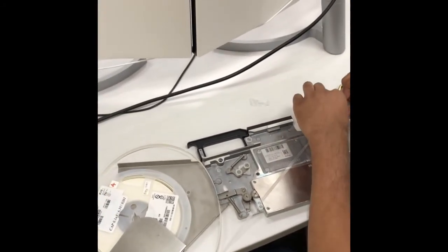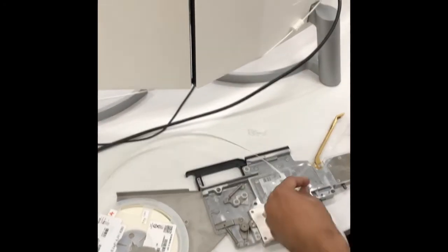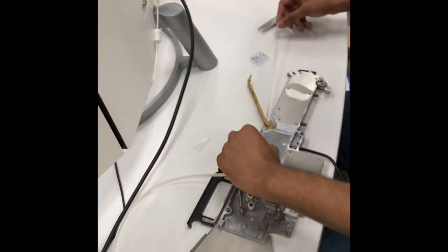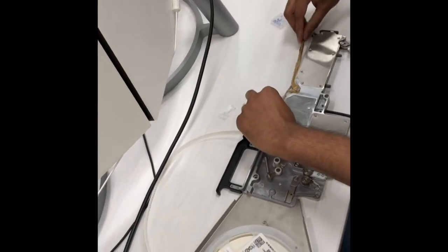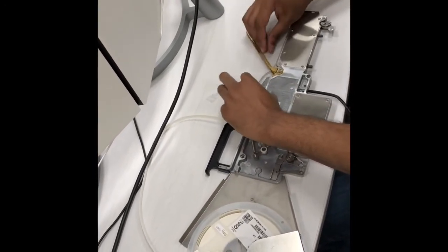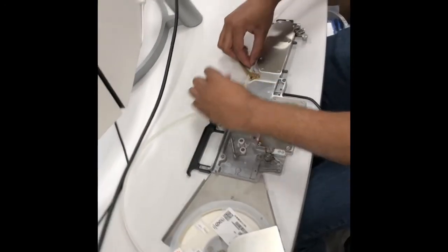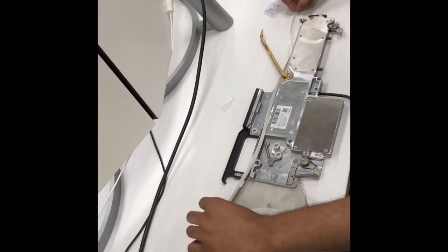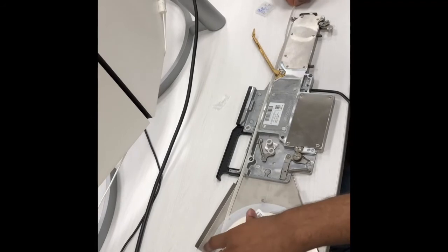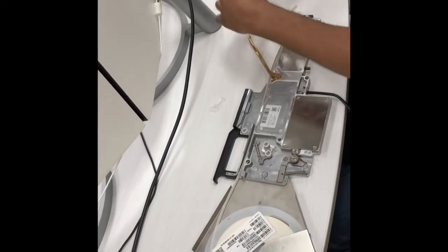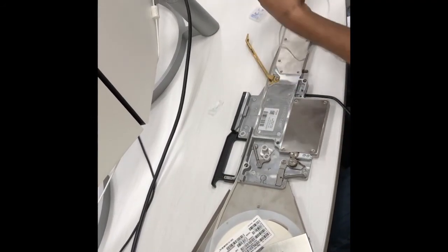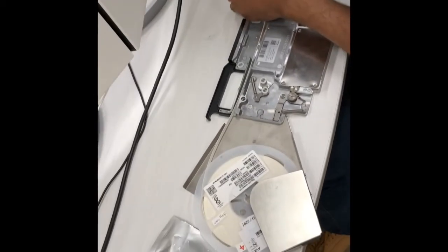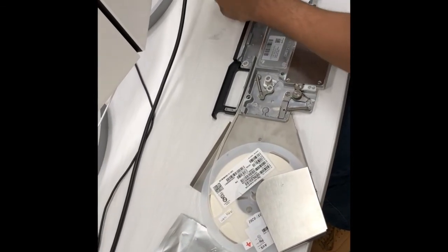I'm going to peel back the plastic. Now that the plastic is free, I'm going to wind it here, wind it here. Push down so I get as much tension as possible, and that's it. What is it that you just did? I put tension on the plastic so that every time it feeds, the plastic pulls back and exposes the components.